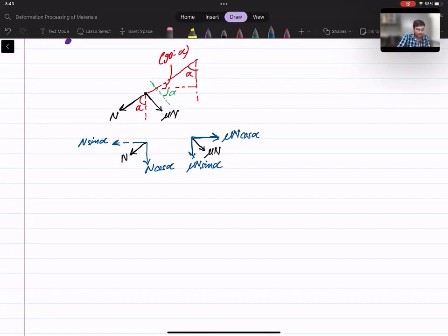So if we consider the loads in horizontal direction, we can take into account the slipping factor, or sorry, the value of load required for the material to pull the stock towards the rolls so that it can get deformed. Okay, so what happens here is Rx, suppose it is the reaction load or load in this x direction, will be mu n cos alpha minus n sin alpha.